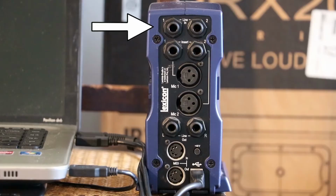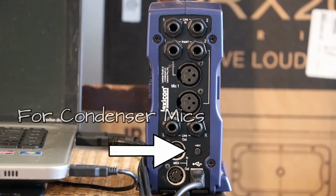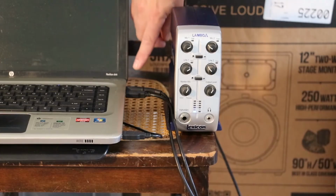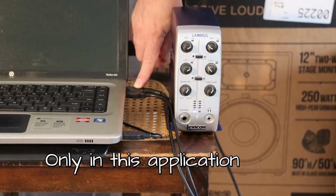On the back of the unit we have 2 1/4-inch line inputs, which can be used in the mono or stereo mode. The insert plugs for different effects. We have the 2 mic inputs, 2 line outs, the MIDI in and out for keys or sequencer, samplers, etc. And we have our 48 volts for phantom power for your microphones. This Lexicon Lambda requires USB power from your laptop. It needs to be plugged into the USB port right next to the power supply for the laptop.